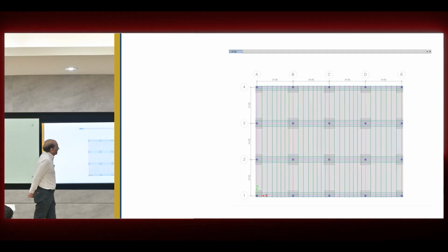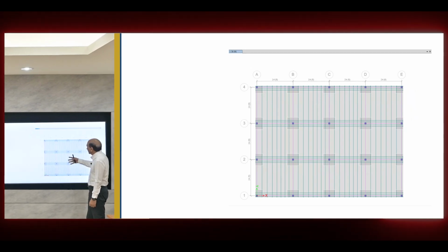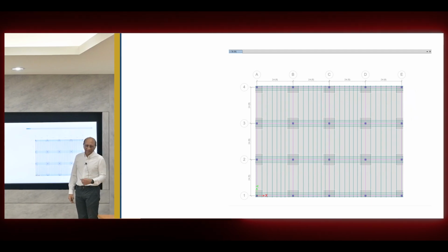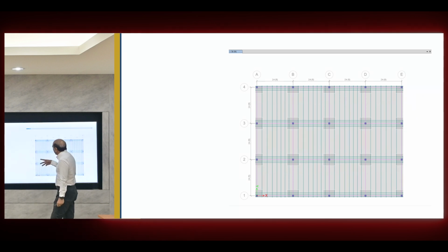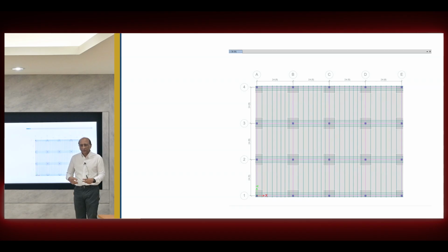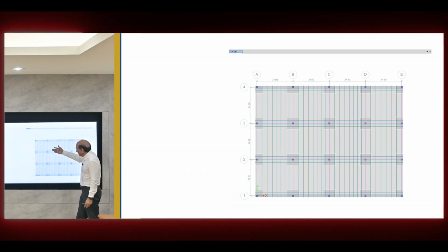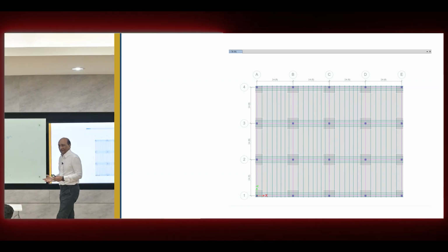Okay, post-tension slab. A post-tension slab is no different from the ordinary slab. The only thing we have done now is that we have added these physical tendons inside the slab. Normally we post-tension the slabs using a banded and uniform concept. In one direction, we put banded tendons, like beams. And in the other direction, we convert a two-way slab system into a one-way slab system.